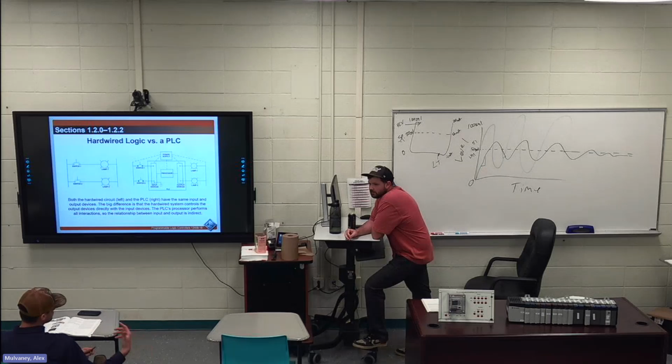Could that be an issue with the PLC? Is that solenoid controlled by PLC? Yeah. There could be, if there's a pressure sensor somewhere else, there could be programming that says like, shut this off if this isn't done. I mean, like, who knows? If this isn't getting a signal, shut this back off. Like you're saying, it should have stayed open.